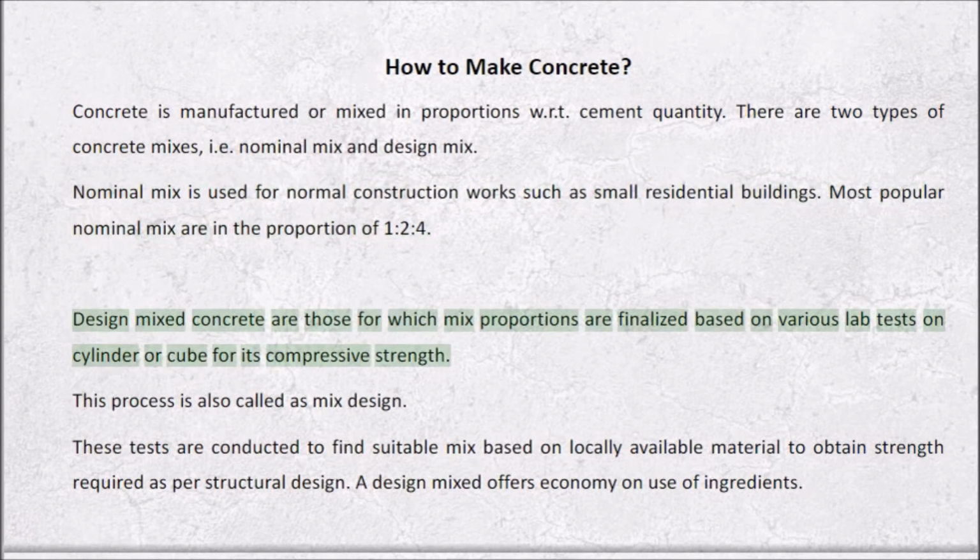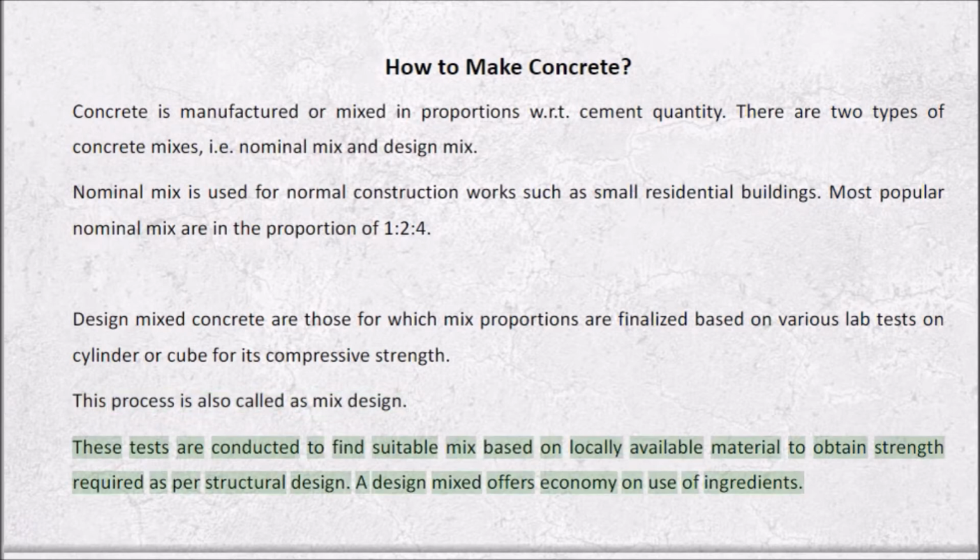Design mixed concrete are those for which mix proportions are finalized based on various lab tests on cylinder or cube for its compressive strength. This process is also called mix design. These tests are conducted to find suitable mix based on locally available material to obtain strength required as per structural design. A design mix offers economy on use of ingredients.